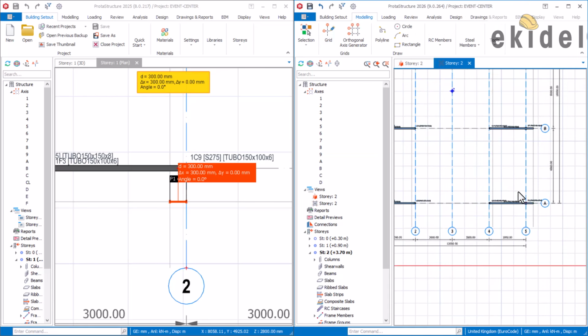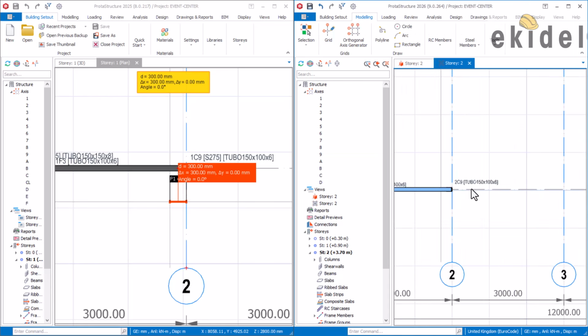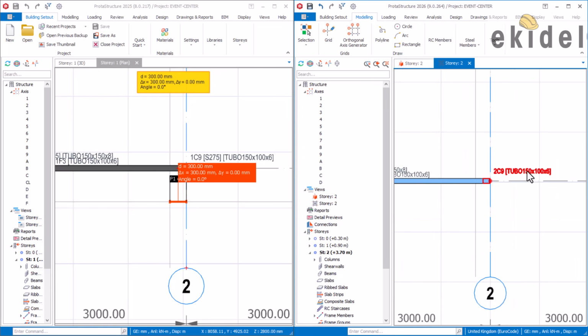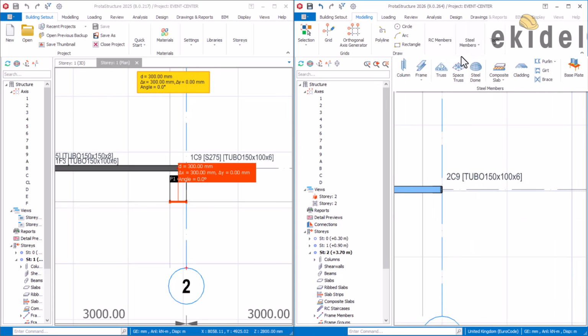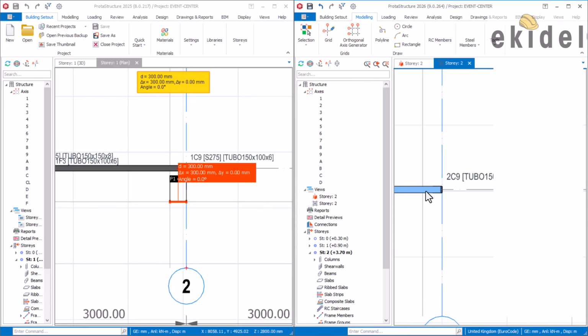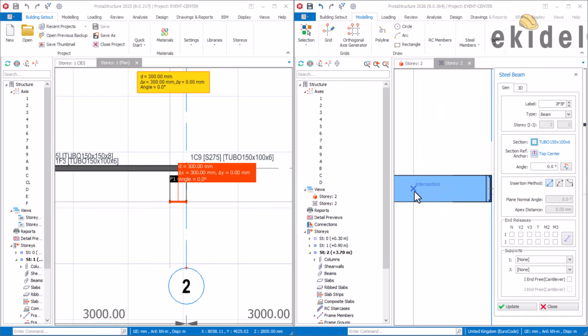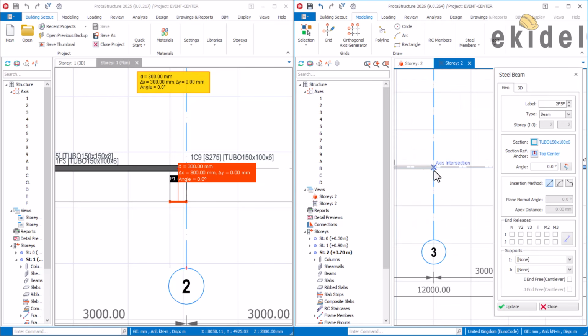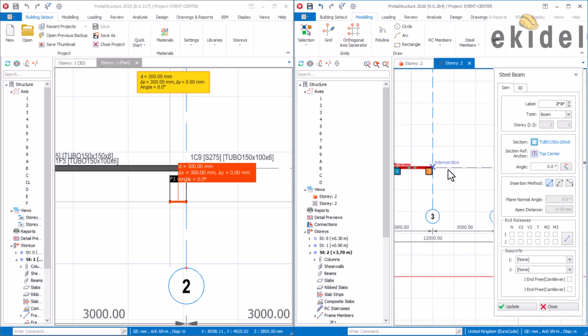So we have established this now. Now that beam is going to run from this point onto this place here. Okay, that is fine. So it is still the same beam section. Click on this, right click here, and then click here. Then start from this point, so we click from this point all the way down here. They will ask a question, just say no. Most times they ask if it will split, say no.